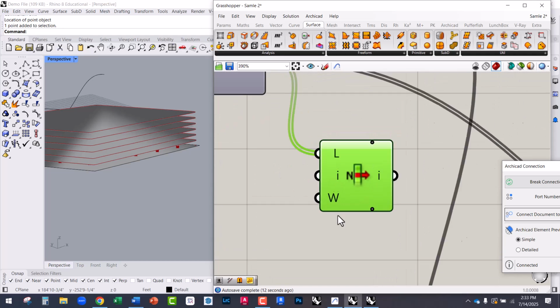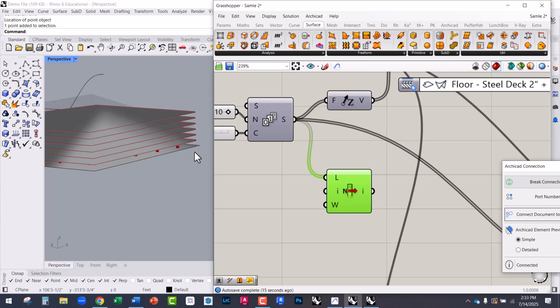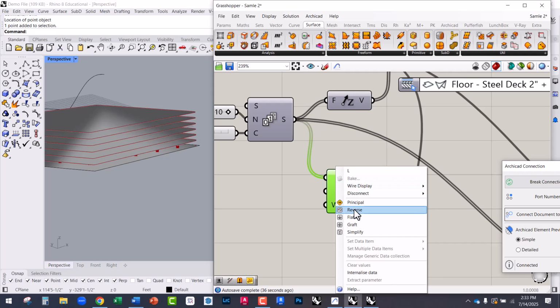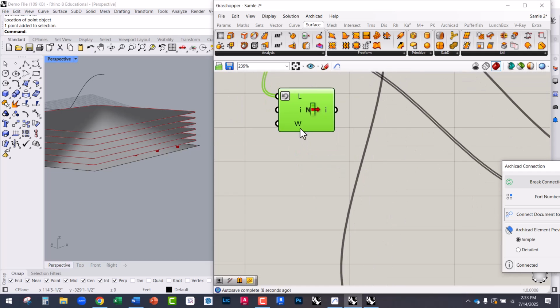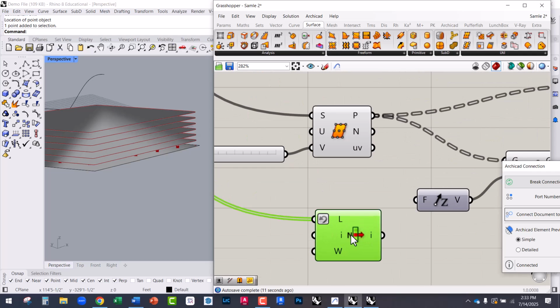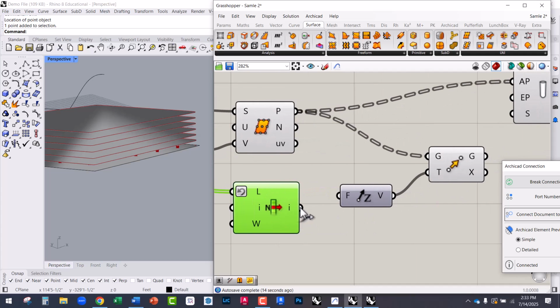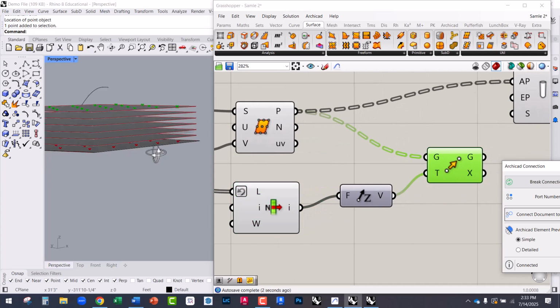Now, if I don't want to have to calculate how many I have and then grab number 6, what I could do is just say, give me 0, which is the first, and then reverse the list. So I'm going to keep this item index at 0, so that'll grab the first, and then when I right click this and hit reverse, it'll now give me the last, which is 60, right? Because we're going from 0 to 60. So that's a little trick to get the last item in a list. And so that 60, that's the value I want to give to those points.